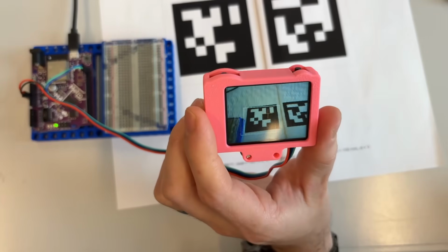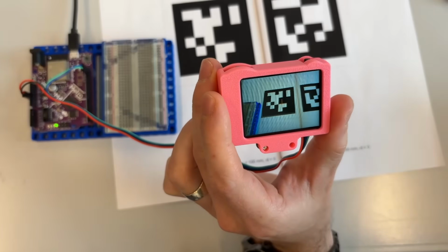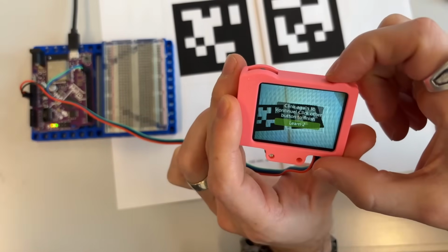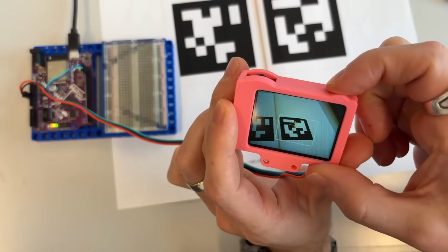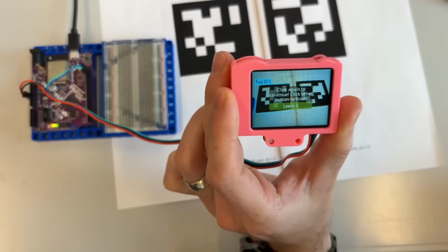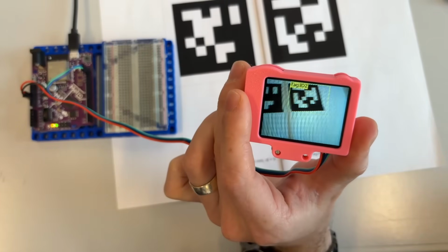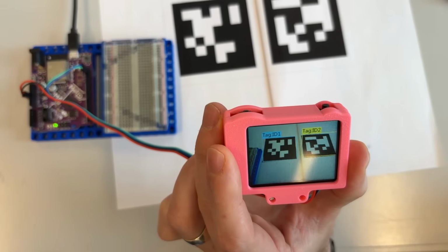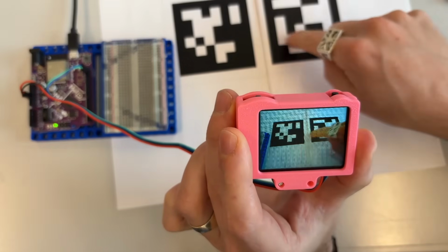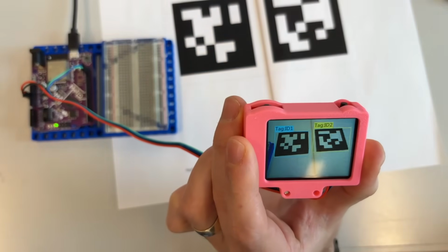And when I'm done learning all my tags, I can recognize up to 6, then I can just simply let the countdown timeout. So I'm going to press 1, notice it recognizes, I'm going to come again, click another button within those 5 seconds, and then we should be ready to just let this countdown roll down. And now we have recognizing tag ID 1 and tag ID 2. And then we can actually see we can have both of them up on our screen. Now recognize that with these tag IDs, the tag ID is the number in which the HuskyLens has learned it.